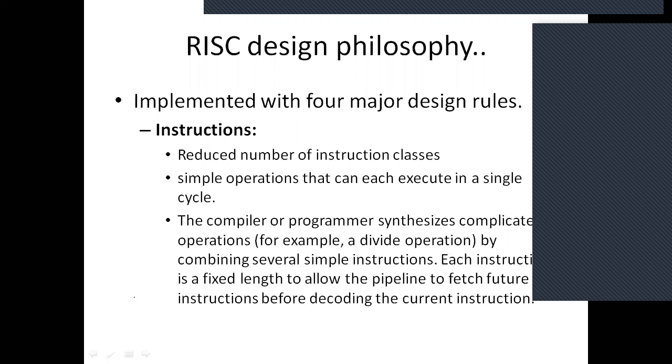Each instruction is of fixed length to allow the pipeline to fetch future instructions before decoding the current instruction. So this RISC feature of fixed length instructions will help to make the implementation of the pipeline concept easier. As we know, an instruction pipeline helps increase the performance of a system.